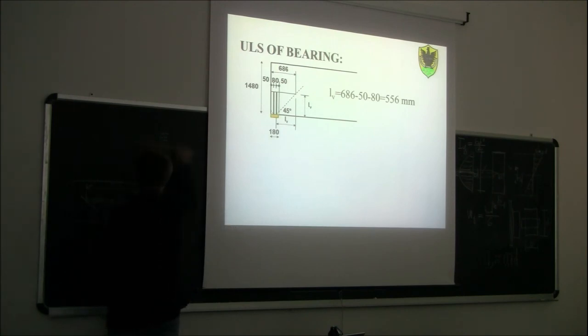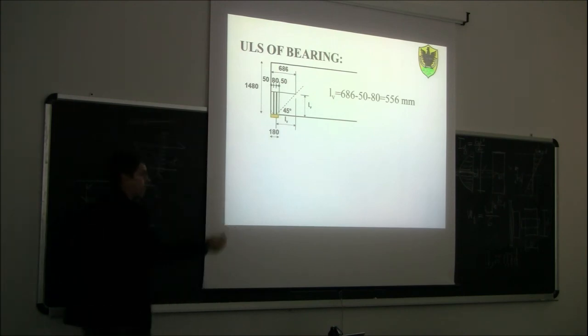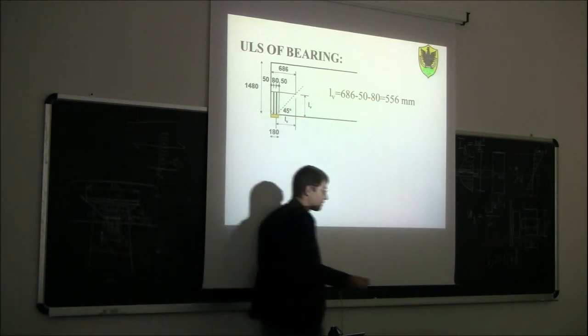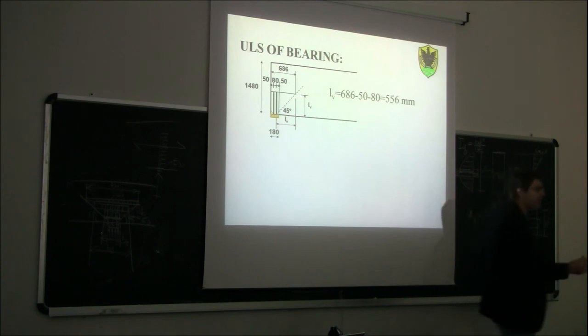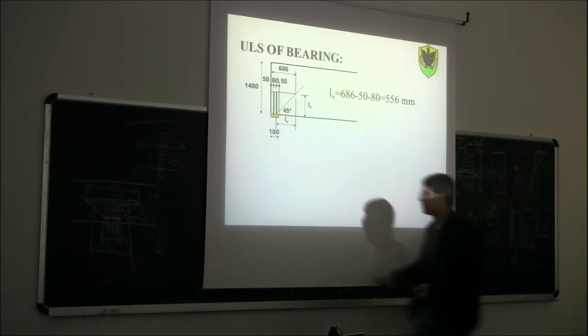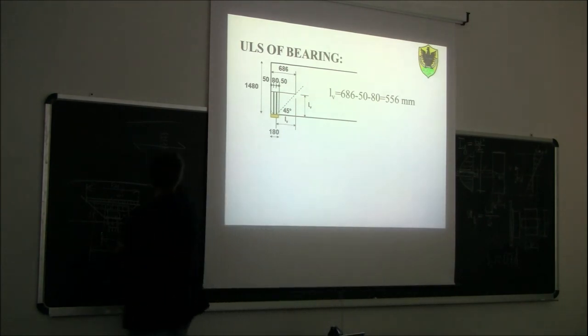The grain is in this direction. E90, if you remember well, is very low. It's 1/30 of the E0, which is 1/3 of the EC, so basically very low. Meaning that these screws cannot provide a very strong restraint against buckling inside.